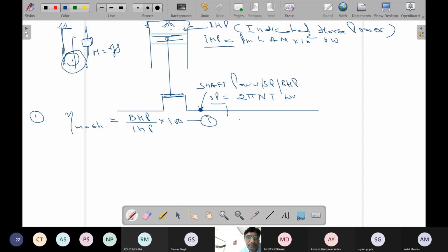Now on a ship, after this main engine you have a coupling here, or a flywheel of course, and then you have what is called the intermediate shaft. This shaft goes from here, supported on bearings, as you can see here. This is called the intermediate shaft. This whole shaft is supported here, with a flange and coupling, and then aft there is another coupling. After that, which I am drawing as a single line, comes the ship side, and here we have the tail shaft, correct?